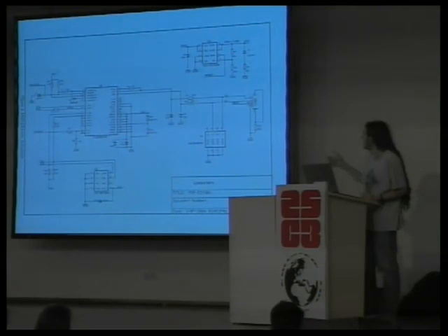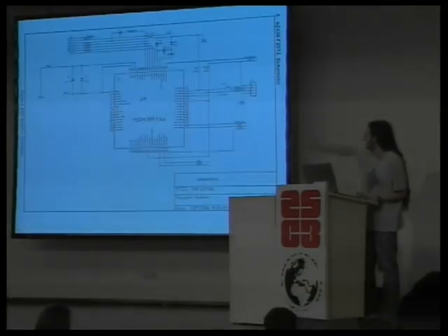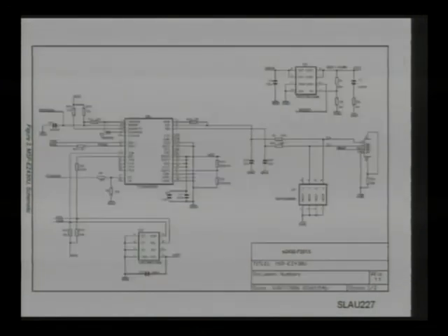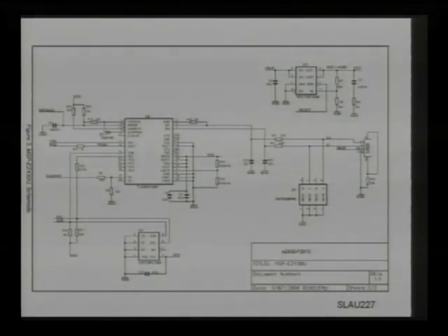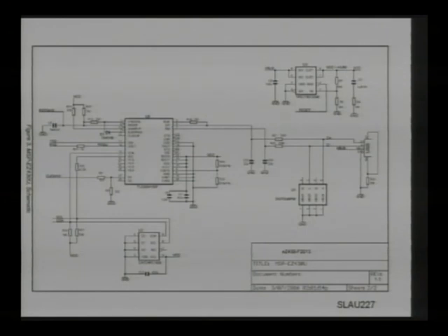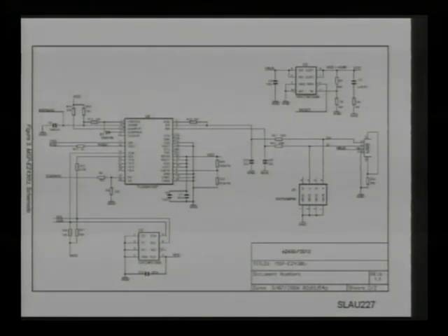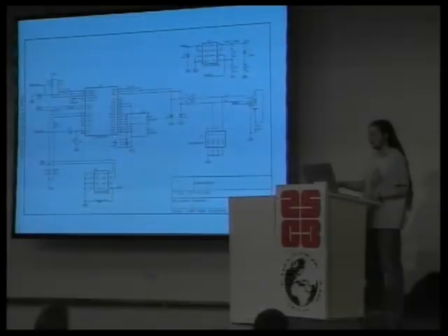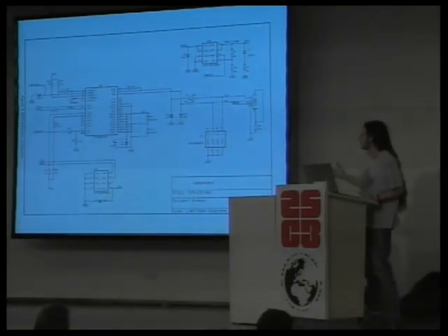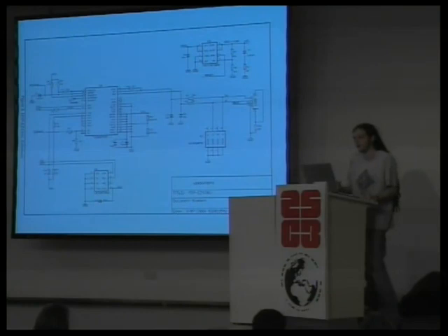But the idea is that firmware for this device resides entirely within the MSP430, which is the CPU of the device, and also within the CAT24 EEPROM, which provides firmware for the TUSB 3410, which is a USB to serial chip, and it's also a CPU. It has an embedded 8051 core, and the reason why the red version of this board won't work in Linux is that instead of using the native USB to serial mode of this chip, TI wanted an extra serial port. So they wrote custom 8051 code, and then matching software on the PC end to allow them to have 2 serial ports from a chip that in hardware is only supposed to give 1.